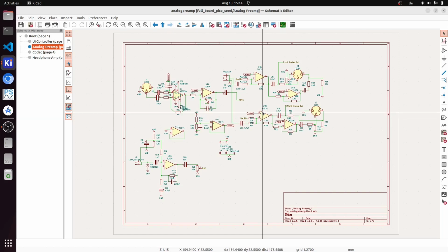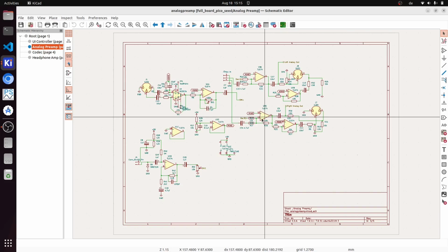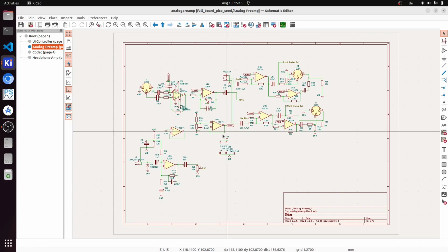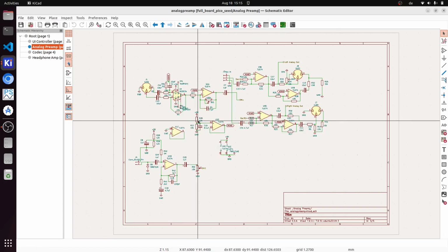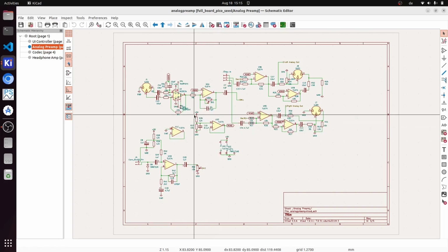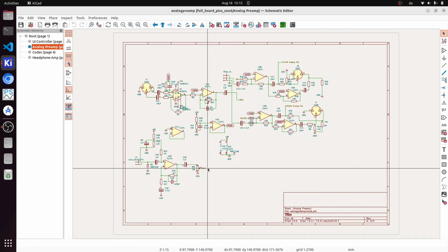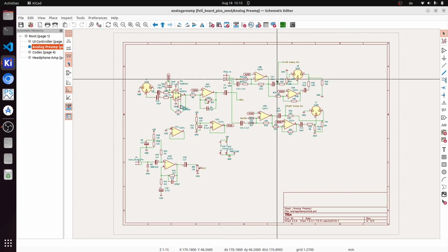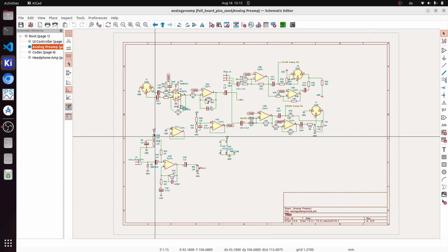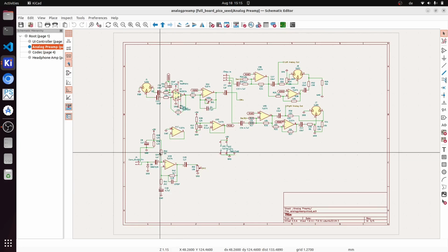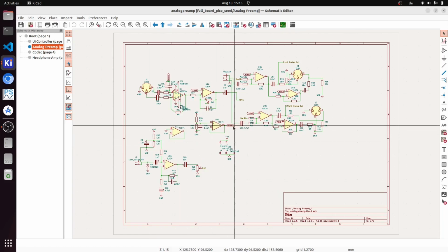By the way, the op-amps are all TL074s or 72s. And well, the analog part relies on a virtual ground, which is created using an input follower with a voltage divider. Well, this is a major change because the first iteration worked with fully symmetric input and output voltages. And of course, what I needed to add is the coupling and decoupling capacitors. The Hi-Z part is also built around a single operational amplifier, and it uses a special virtual ground which is not shared among the others.